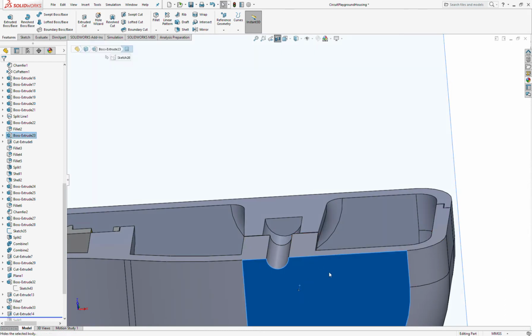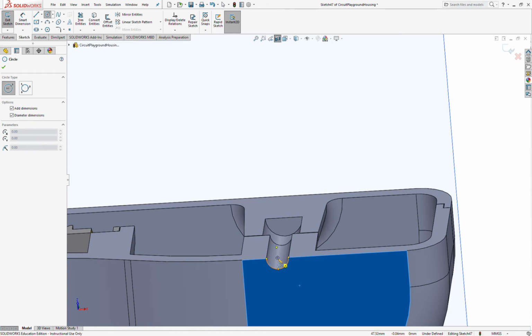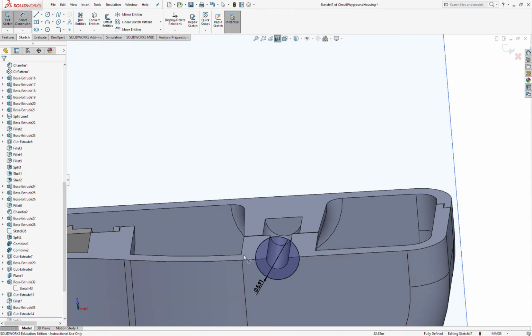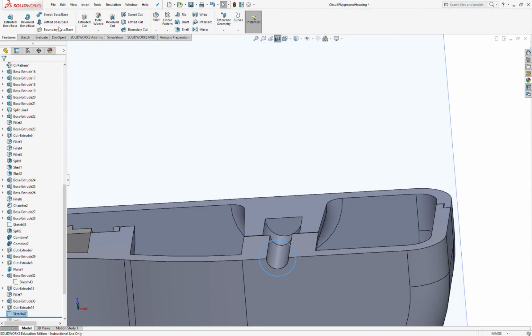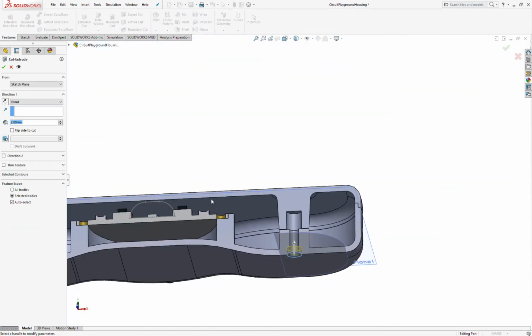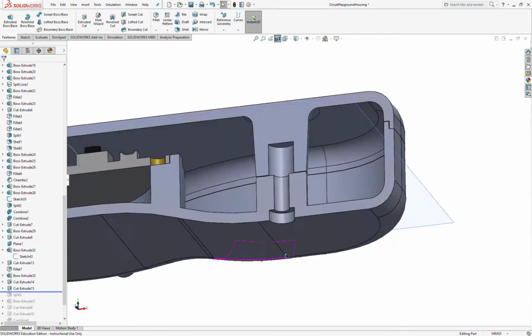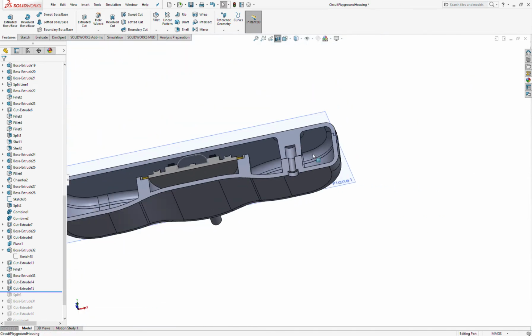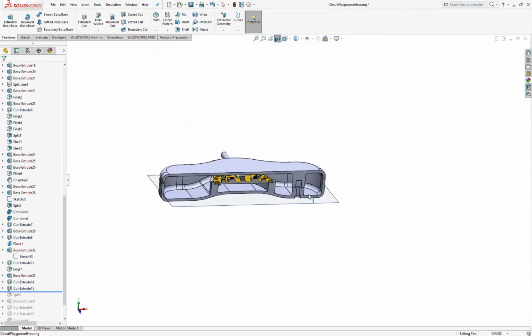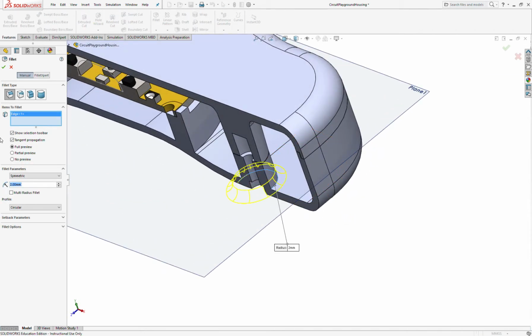And then we're going to come in on this bottom side. We're going to add another hole. Make it 5. No idea. And we're going to extrude cut this in 2 millimeters. So this would be for the head of the screw, so that when it goes in, it sits nice and flush with the bottom. So last thing to do is to throw the fillet around the edge.